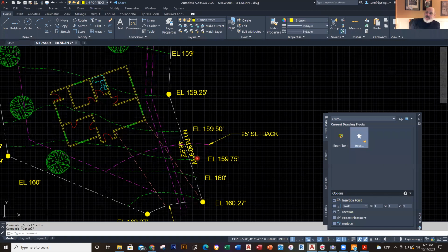But here's the point. You use the metal detector to find that set capped iron rod. Those things have been set into the earth as landmarks, essentially an immovable point to which you can always refer. Therefore, legally, that is how land is reckoned. That's how taxes are levied. That is how people pay for square footage and acreage. That's very important, so you've got to find the actual origins.